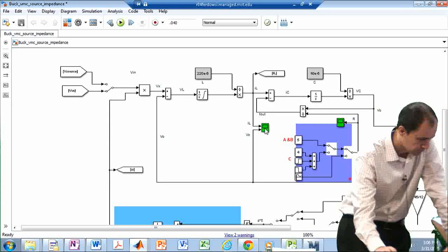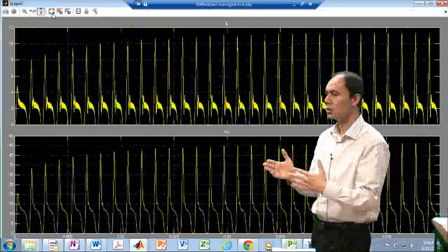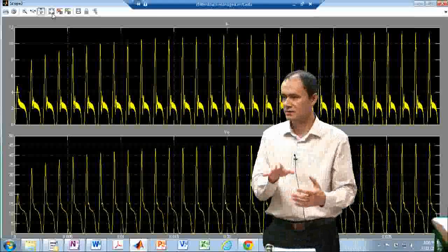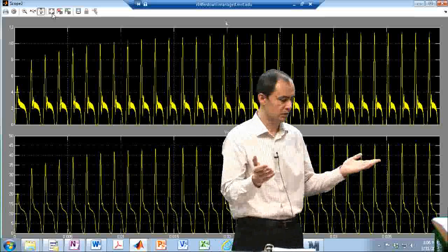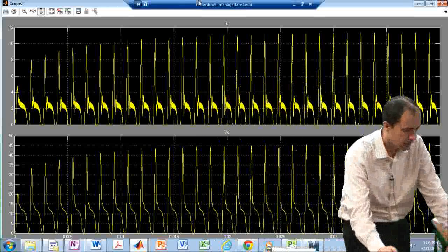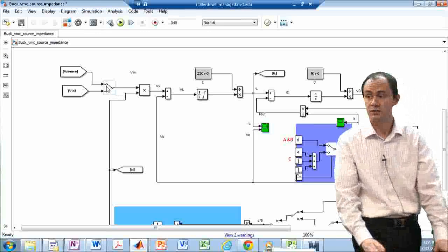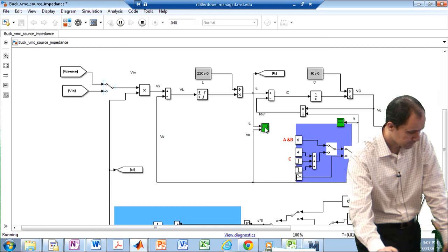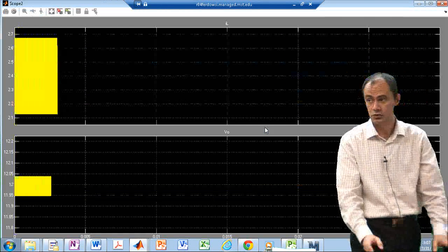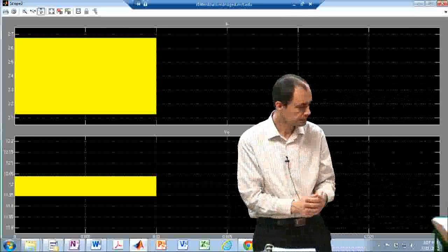All right. You can see that the system is going all over the place. I just added the filter to the classic voltage mode controlled buck converter, and it basically went crazy. And if you don't believe me, just bypass the filter and look at it now, and it looks normal. So you just add the filter, it goes crazy, take the filter out, it goes normal.